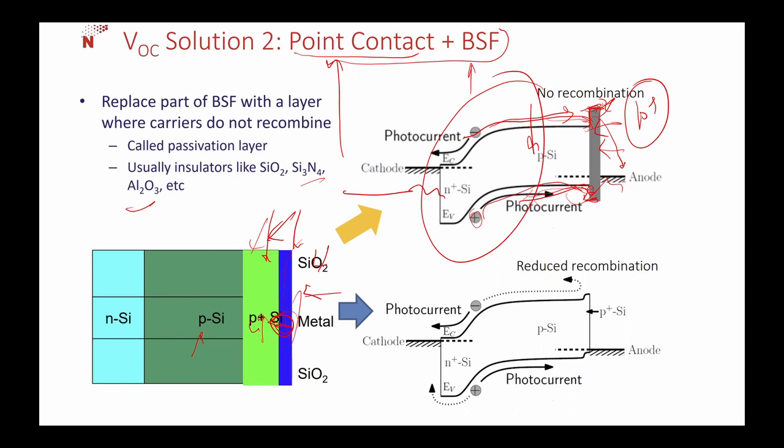But if you are going for the long term, obviously you are benefited for the long term, but they are not cheap, because of the method of deposition. This n plus and p plus region are done with diffusion. To do these things, you need a very high quality clean room. There should not be any impurities in that. To coat the SiO2, you need big machineries.